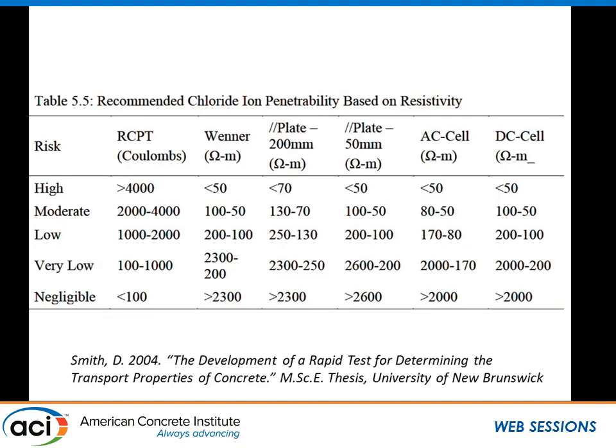That slide there just compares different measurements with rapid chloride permeability tests, the scale we're used to, and just shows you the sort of target values you should be looking for electrical resistivity to give you a similar kind of measurement. I'm sorry if I took too much time, but I'm a slow starter.